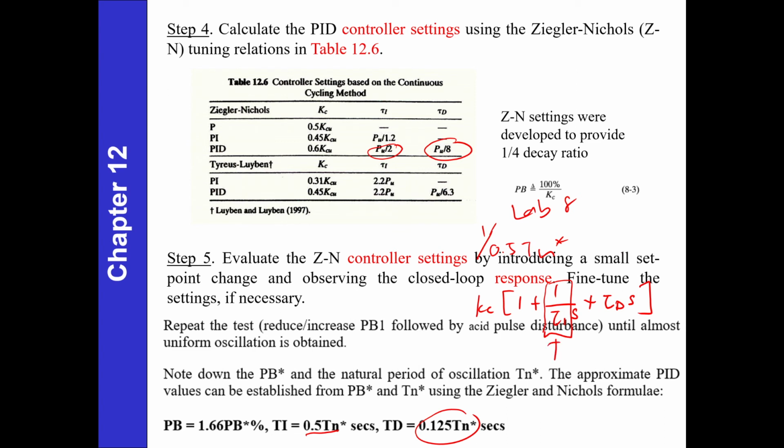That's why for the value of I in Simulink, just in Simulink, you have to take 1 divided by this one. Because of this equation, because we have PID in a Simulink, the PID controller in a Simulink block diagram, the value of I is actually this one. Hope that you can still remember. If you get confused, you can refer back to that video.